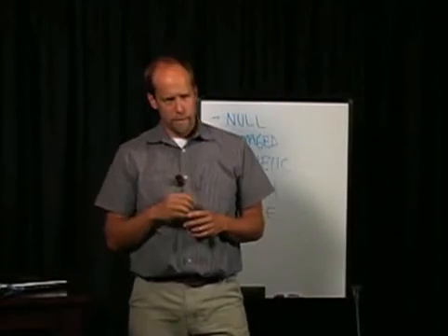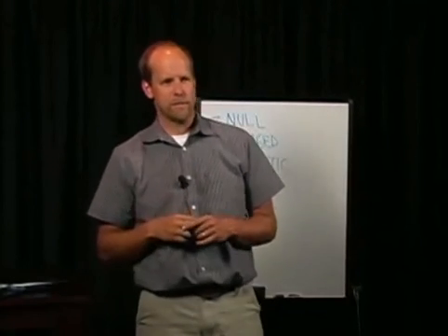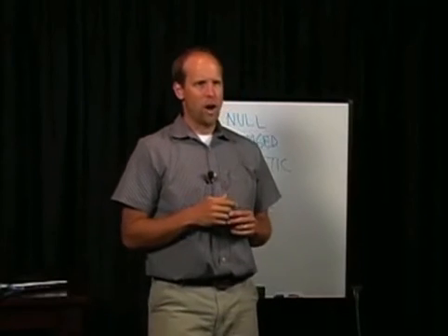Number 4, try to arrive at the inspection 15 minutes early. Meet, greet, show proper identification to anyone present. If the owner of the building is available, ask the following 7 questions. 1, are you aware of any active water penetration or intrusion at the building?